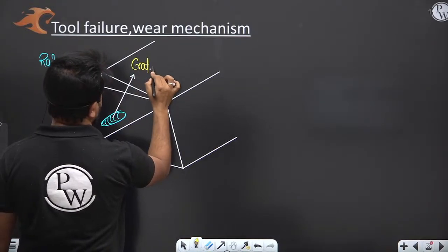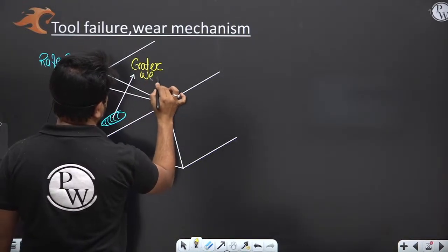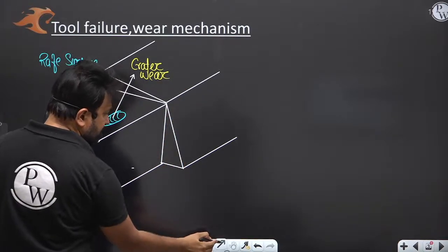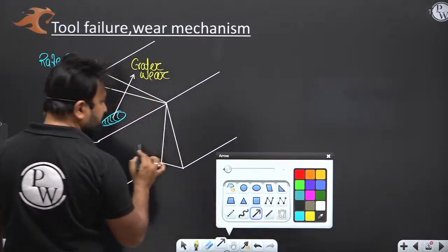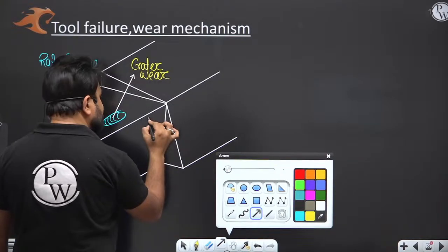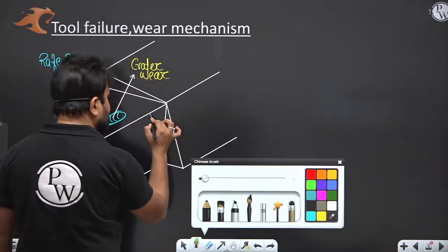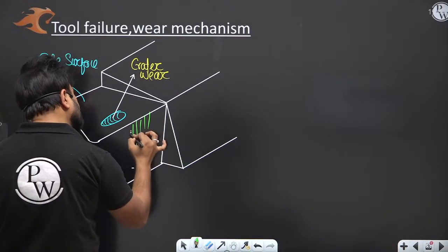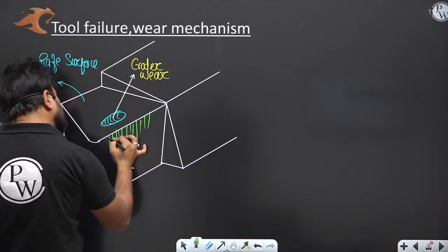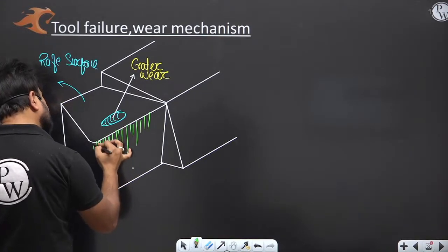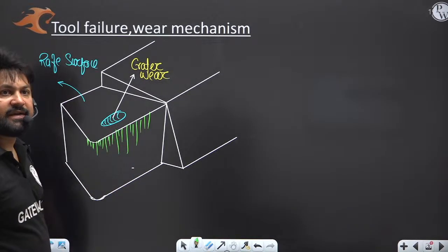And there will be wear just below the side cutting edge, usually on the flank, and a little bit on the nose.